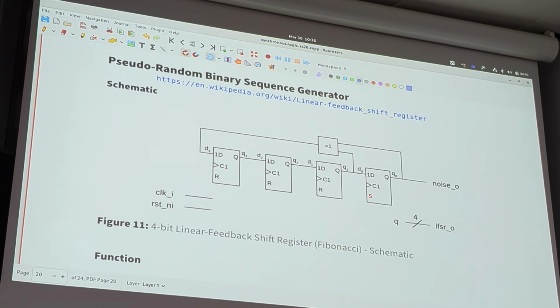Just one, for example, depends on where we connect our feedbacks using XOR gates. And depending on these XOR gates, we get different output patterns at our output, as a serial data stream, which we call pseudo-random noise at the output. So this feedback path is often an exclusive OR, but can also be an exclusive NOR.